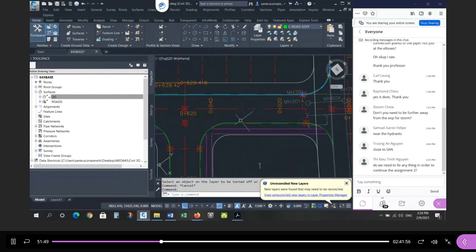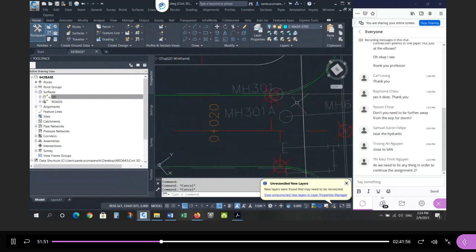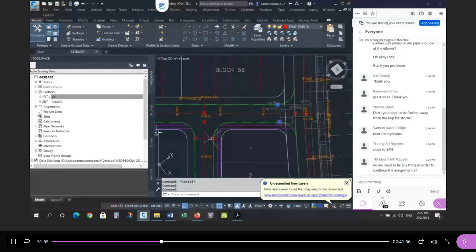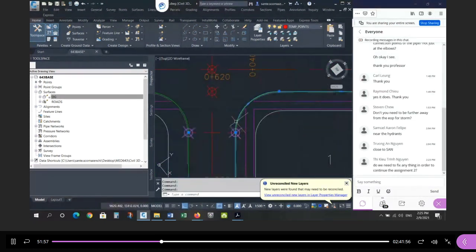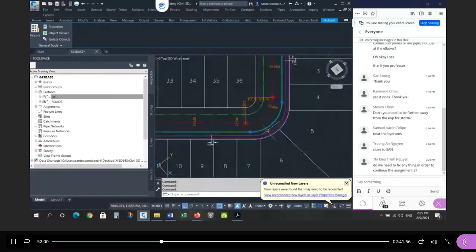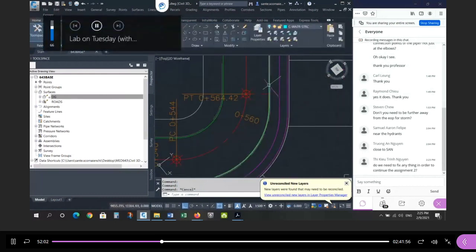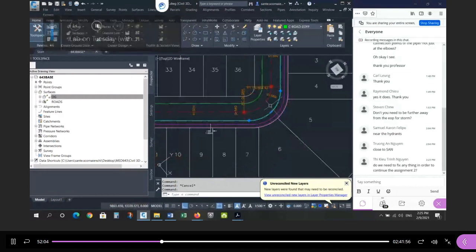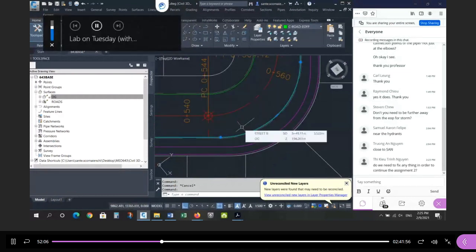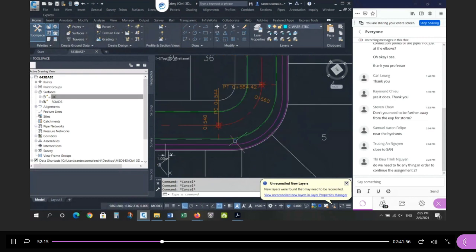If you draw the edge of pavement, this green stuff, in the wrong spot, then these key points in the plan, which are based on the edge of pavement location, are the key points in the profile, right? If this is drawn incorrectly, then you can't design the profile of the road properly. You can't design the profile of the gutters correctly, which you will have to do.